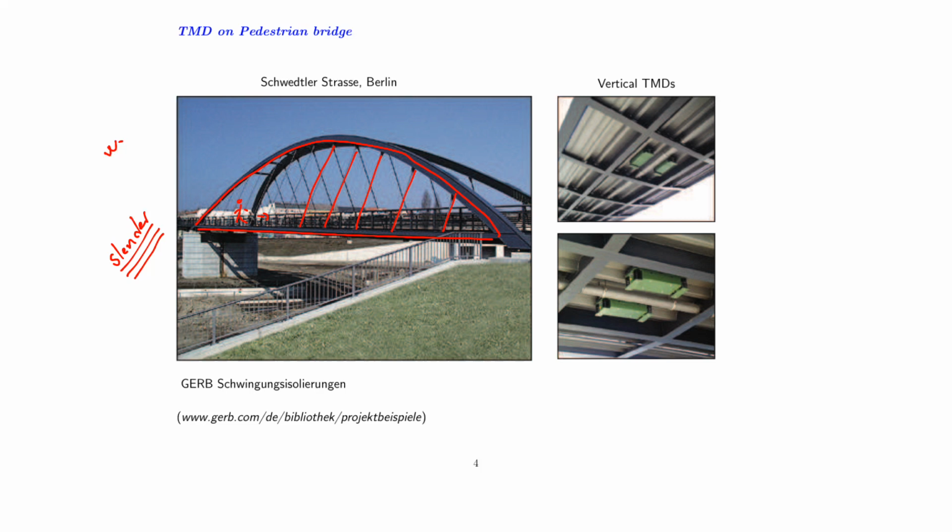So it could be walking, the Millennium Bridge scenario on the opening day, but also running, marathons in the city of Copenhagen or Berlin in this case, and bridges should of course also be comfortable with respect to running. So for many bridges, it's initially the vertical displacements that are a problem. As you can see underneath this bridge, you have installed these green devices. They are probably easier to identify on the bottom picture here.